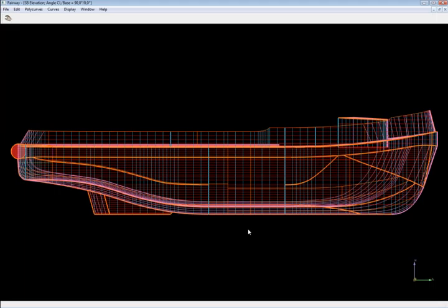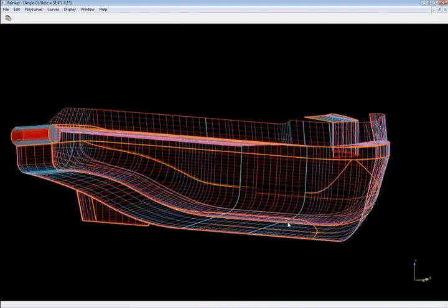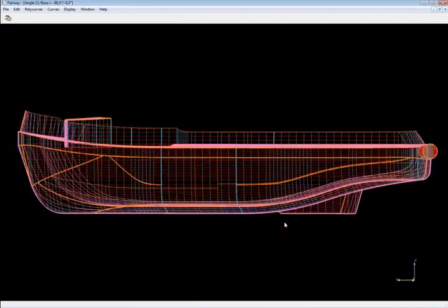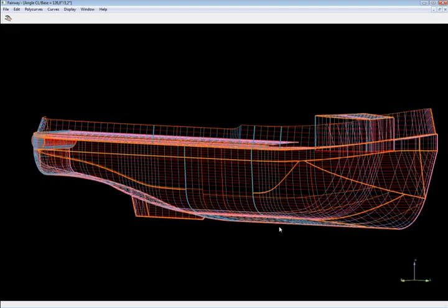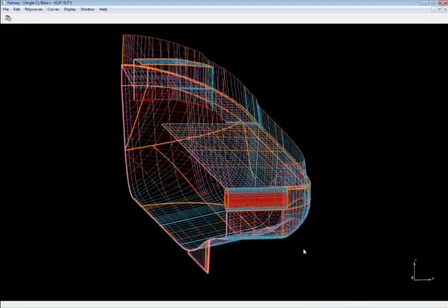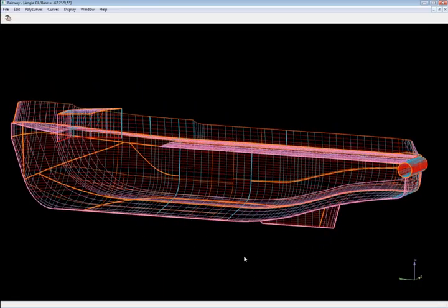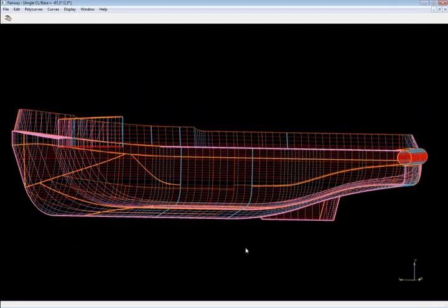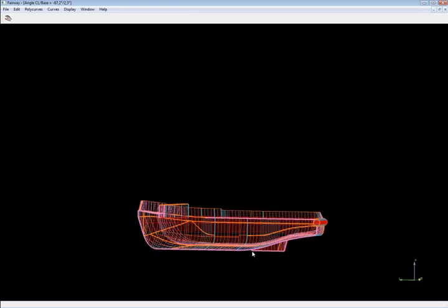There's one more rotation trick. You can have the model spin on its own by releasing the mouse buttons while the mouse is still moving. It will continue to spin until the middle mouse button is pressed again. You can quickly shift between pan, zoom and rotate by depressing and releasing the modification keys or buttons. There's no need to release the middle button for that.